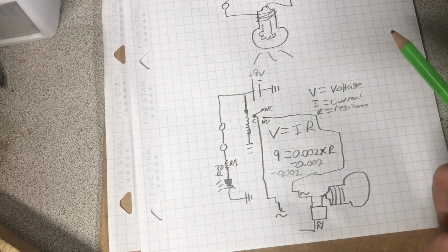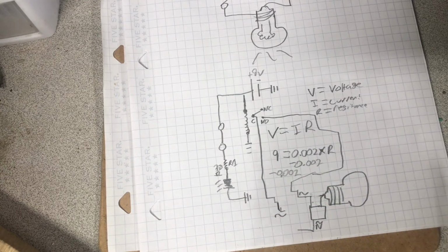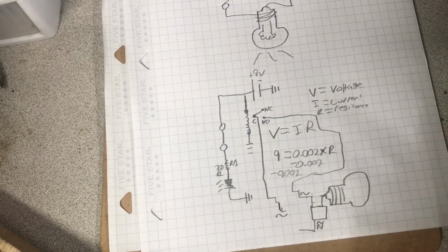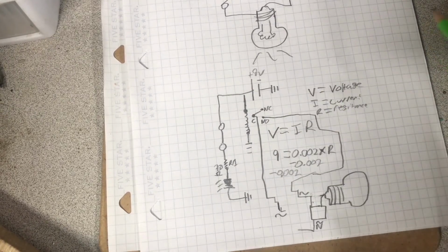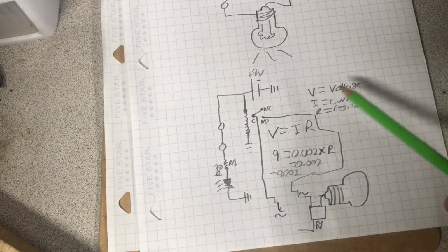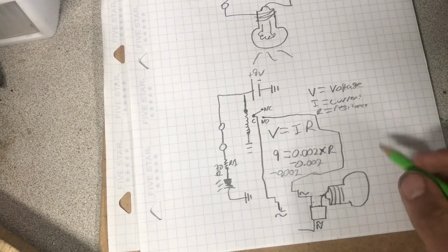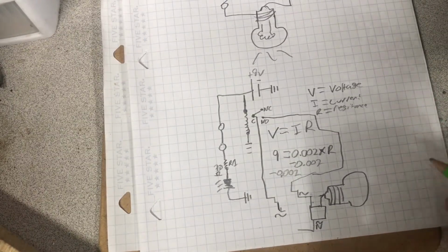So any load is usually not going to short your supply. Unless, in some AC applications, say you connect the secondary of a transformer instead of the primary, AC is not going to like it, and it's going to think it's a short. So most likely you'll melt something out, or you're going to trip a breaker.